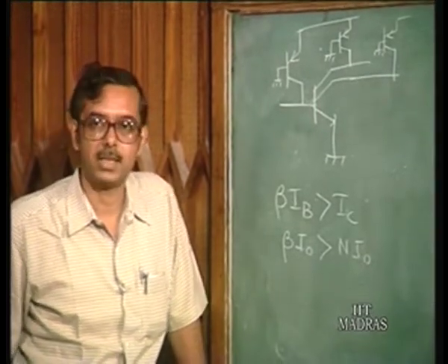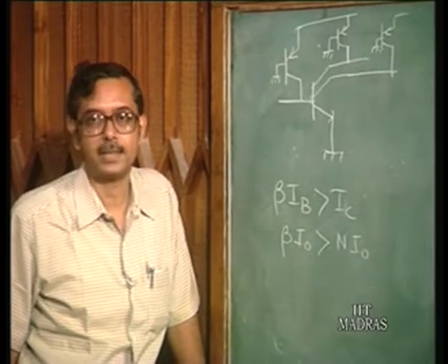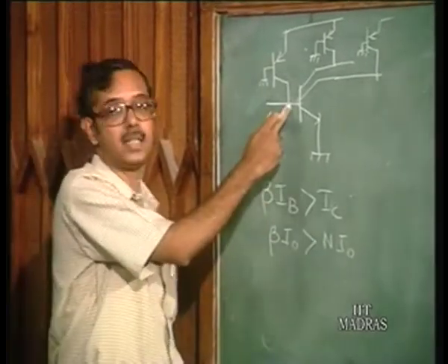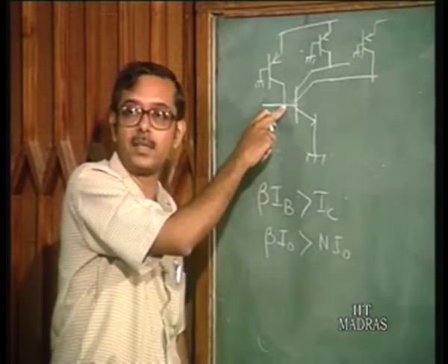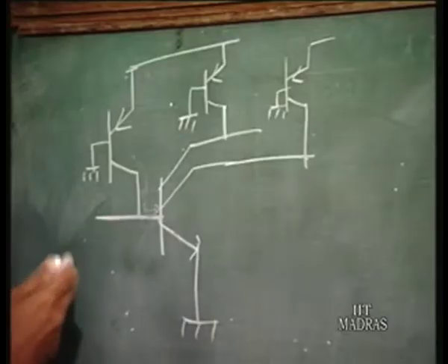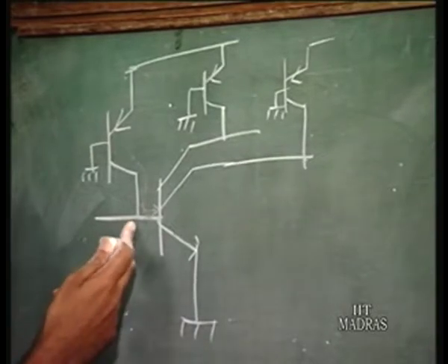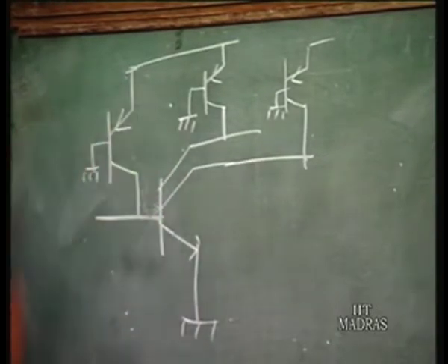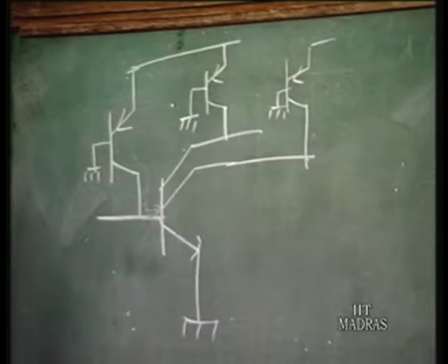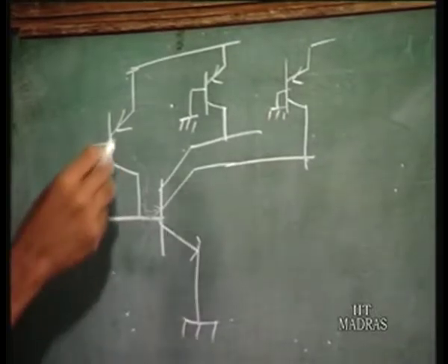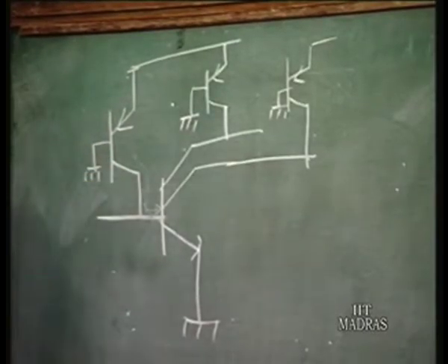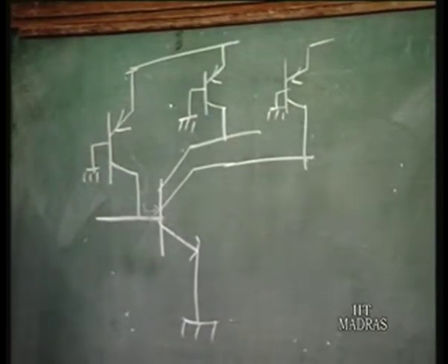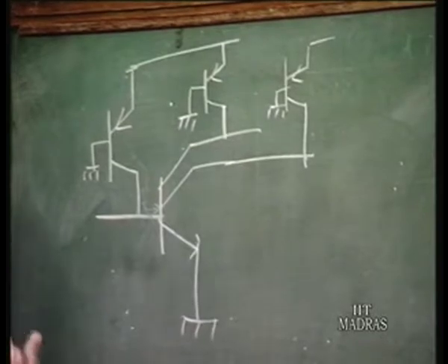But this is very simplistic, because when this transistor goes to saturation, the base voltage is around 0.7 volts or so. So this is high. What is the condition of this PNP transistor? The base voltage is high, the base emitter drop is high, as well as the collector to base voltage. So this transistor is in saturation, in fact deep in saturation.